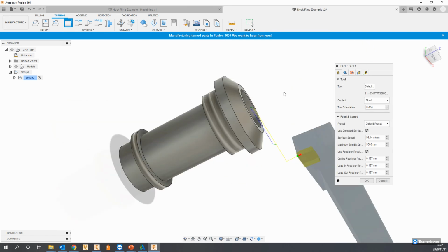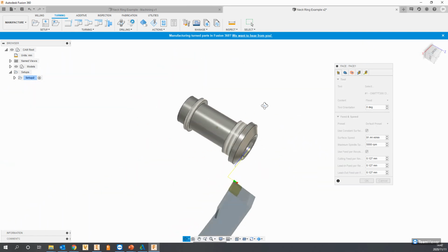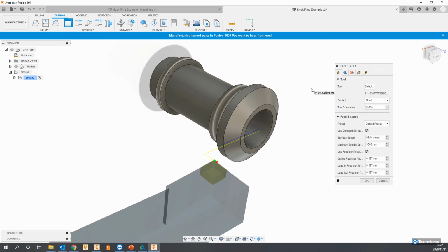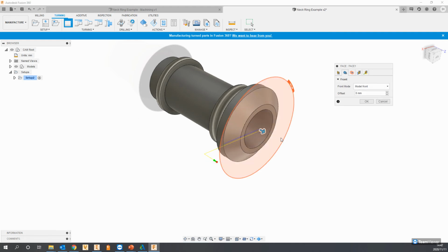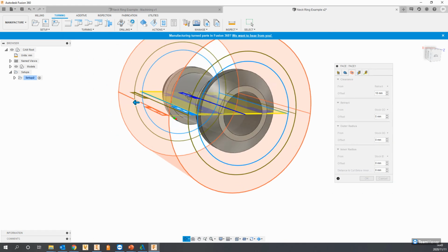You'll see that it inputs our tool in here. I've just orientated it the wrong way. Now that you can see, it is going to start generating toolpath based on that. I can override my feeds and speeds if I want to, but I'm just going to go to the next tab. You'll see that since this is a facing operation, it's going to detect where the model starts and it knows where the stock starts, and it's going to clear all of that.